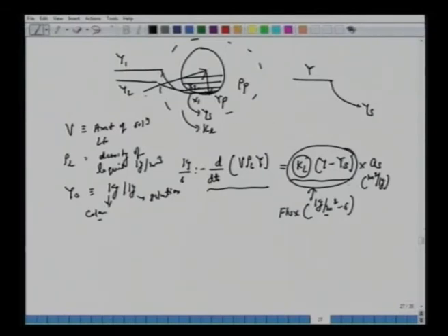So we are talking of this flux across this. So meter square per kg multiplied by this W. What is the weight of this solid adsorbent? So this is W kg. Okay, so see, that is kg per second. How many kg per second of color is lost? Whatever is lost here is gained, or transferred across the film to this solid surface. So we have the flux, kg per meter square per second, multiplied by meter square per kg, multiplied by W, to make it kg per second. So that's the solid balance.